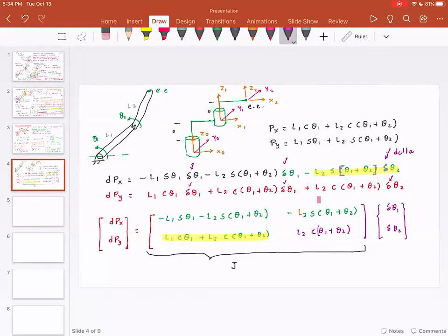So that is the power of the Jacobian. Now, what it means is once you have the Jacobian, you can find out the forces at any equilibrium condition. Imagine that you have a robot that is very slowly moving an object from point A to point B. So it's quasi-static, the same term that you see in thermodynamics.